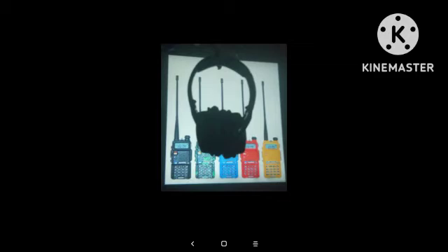Number 6. Why is a 5/8 wavelength vertical antenna better than a 1/4 wavelength vertical antenna for VHF or UHF mobile operations? A 5/8 wavelength antenna has more gain. Number 7. What is an advantage of downward sloping radials on a ground plane antenna? It brings the feed point impedance to 50 ohms.